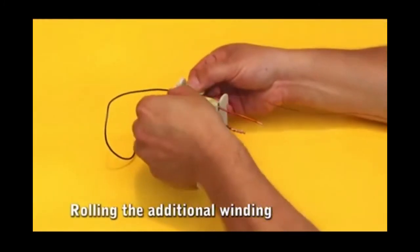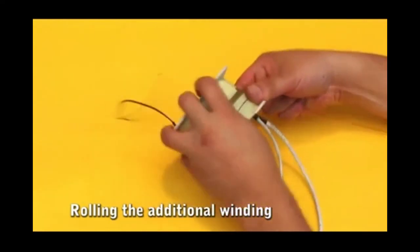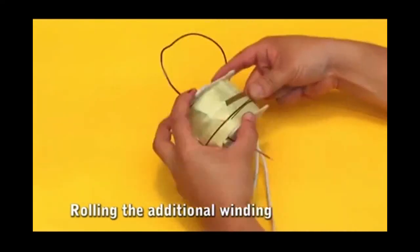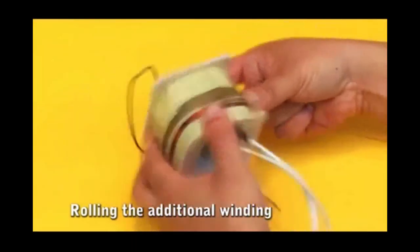Like the previous windings, it's necessary to weld a wire to the copper wire, and use masking tape, to wind the additional winding. The wire is wound from bottom to top to adjust the starting point with the turns of wire.